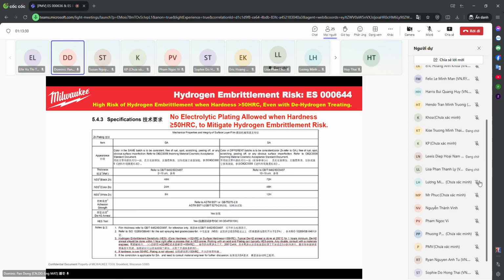We don't want to get into the huge trouble of hydrogen embrittlement. So here, a summary again. Any surface treatment parts with electrolytic plating of nickel and zinc or acid pickling, if the steel's surface hardness goes up to 50 HRC or higher, is not allowed unless you get approval from TTI group. This TTI group means engineering group, not only the QA group. Please be aware of that.